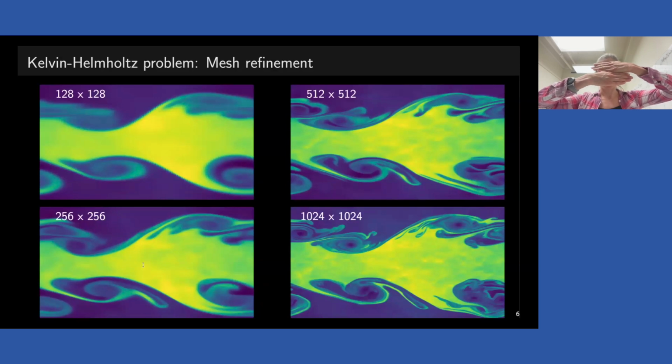And then the initial velocity field, so this is the compressible Navier-Stokes equations that you have seen before. So we'll need to specify the velocity field. It's a shear flow, so it goes in one direction in one of the bands and in the other direction in the other band. And because you often have some small inaccuracies between the layers, it may not be exactly smooth, you get instabilities and the formation of little eddies that shed off. And so that's what you get at a later time.